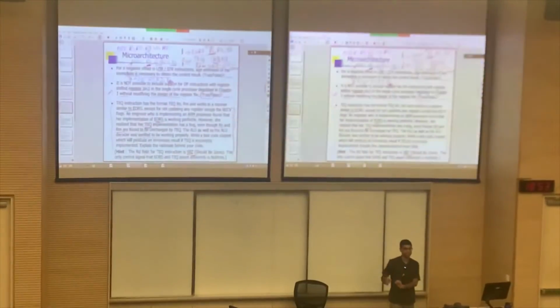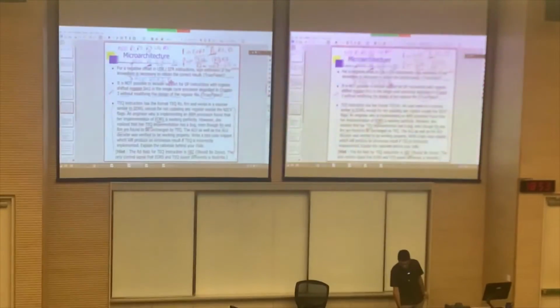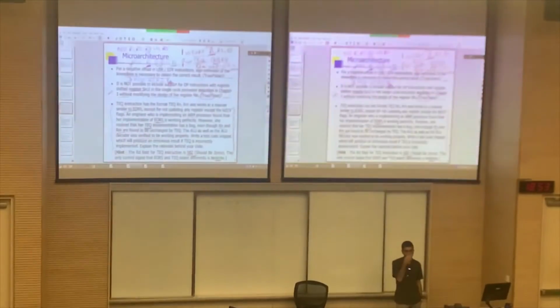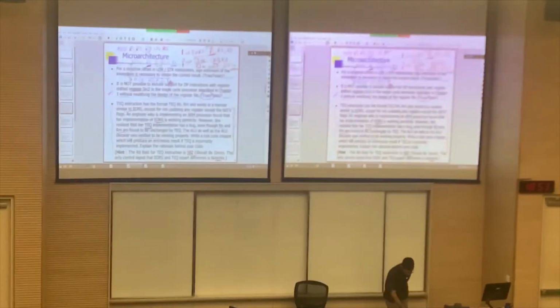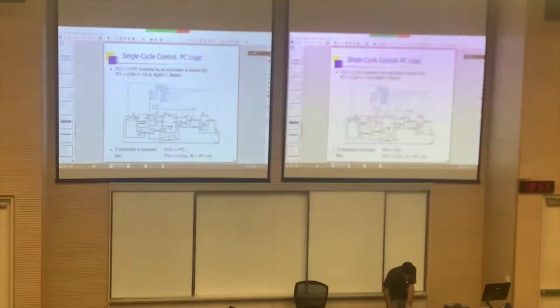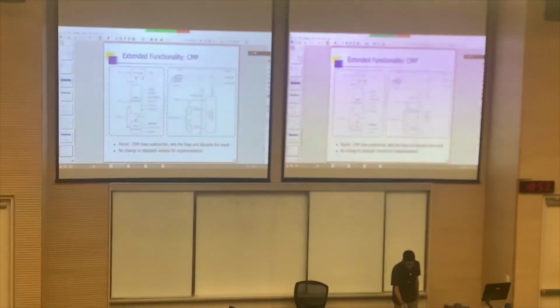As long as there is an instruction which makes use of R0 after TEQ, it's already a good test program. Of course, the instruction should do something meaningful, and then you will see that the result is not what you expect. So basically, the no write implementation for some of you was wrong, or no write was not connected to the reg write. If you go to this chapter, no write is a signal that should be asserted for instructions which do not modify registers.